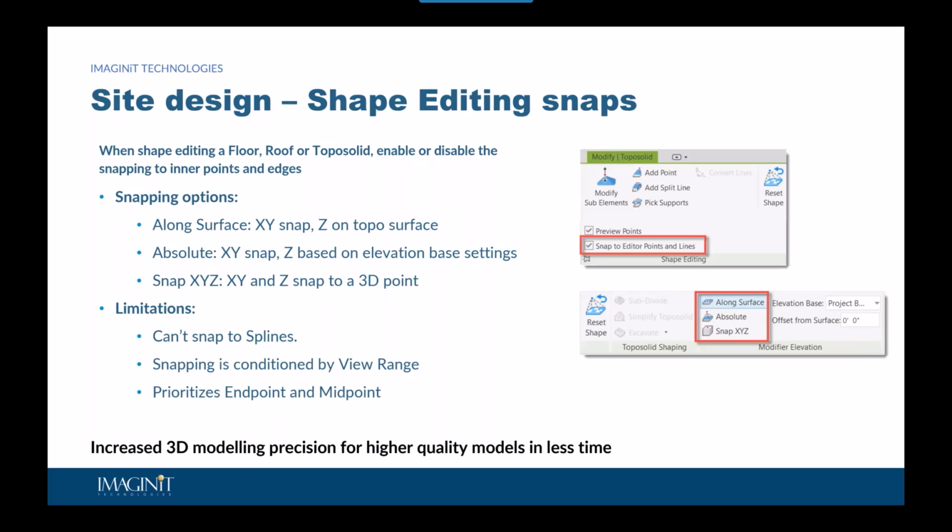Limitations. Snapping cannot detect points of a spline line. Ensure that the view range is set to display the entire reference object in that scenario. The snap sequence prioritizes the midpoint and endpoint. When snapping to a loadable family, switch to a 3D view to ensure that you snap to the appropriate point.